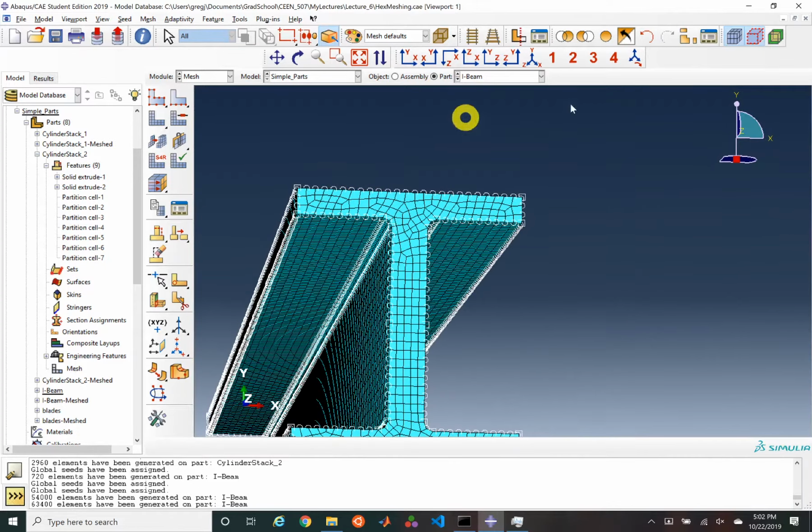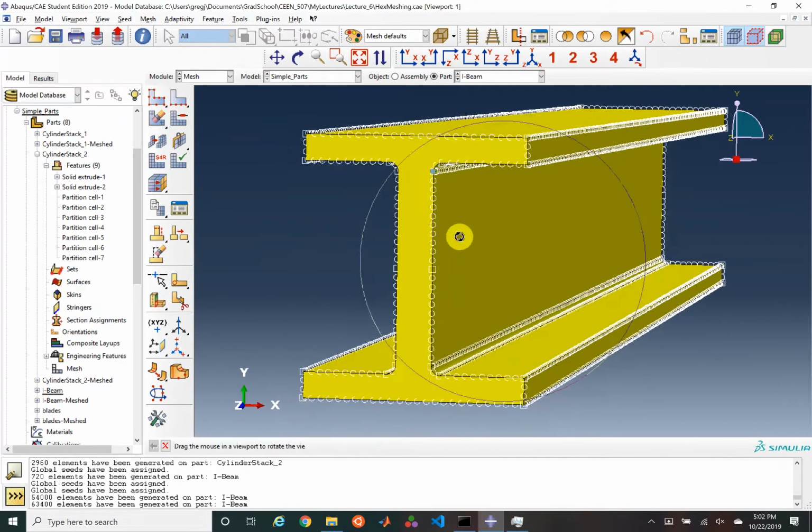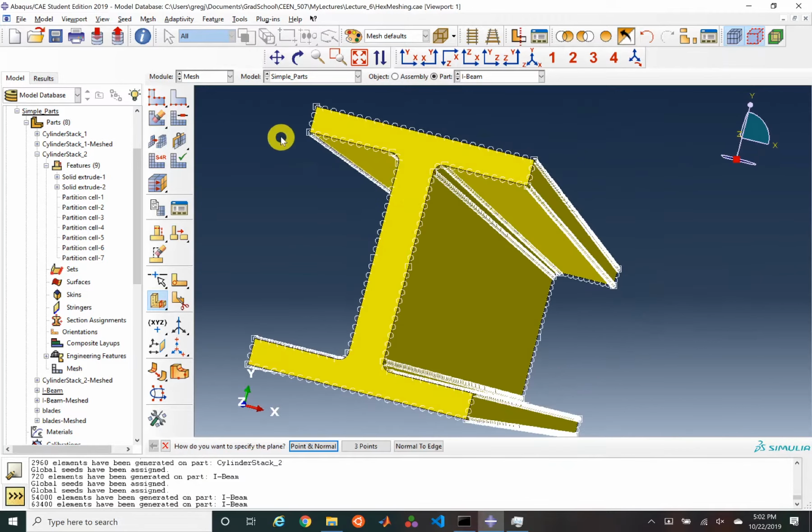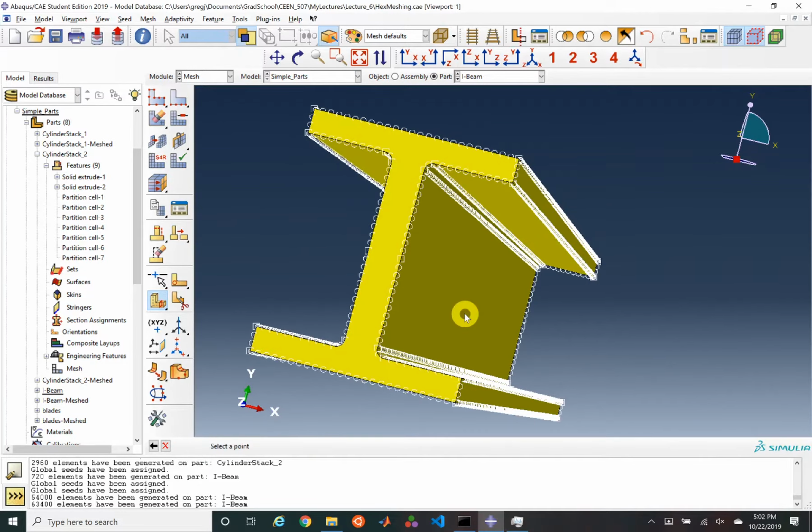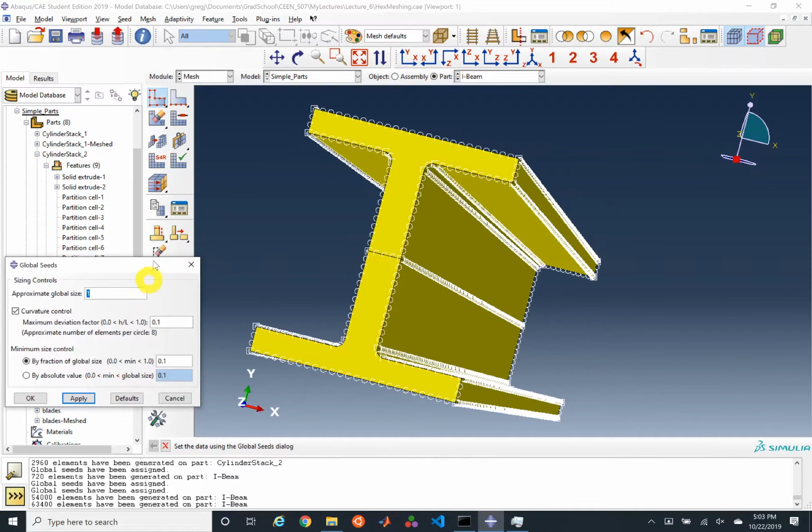But let's go through and do some decomposition on this geometry. So I'm going to delete this mesh, click and hold, and drag over to delete the mesh. The first thing I'm going to do is there's obviously some symmetry here, so let's cut our geometry by the big symmetries that we see. I wish I could turn these off. At least these to be large again.